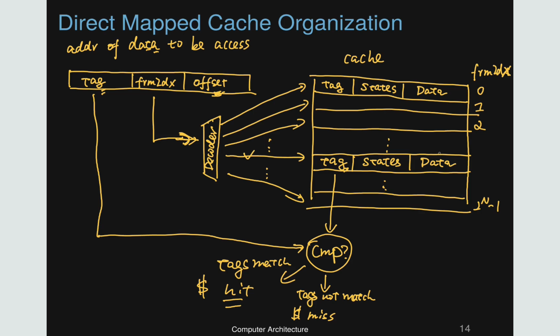It's usually only 64 bytes, which is much larger than the functional units in the CPU. Therefore, we usually only request a small part of the cache line. So the last thing we need to do is extract the part of the cache line that is indeed being requested. We usually request maybe a double or an integer, so we do not really need all of the 64 bytes.